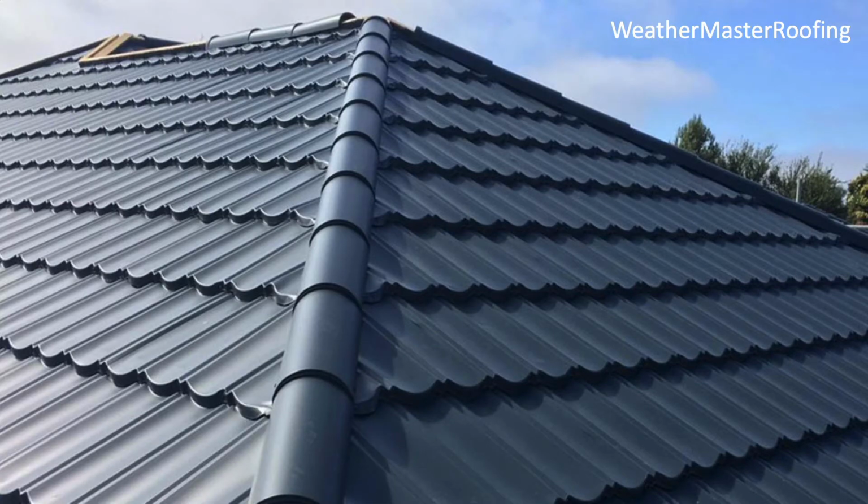So roofs do it tough. They get really, really hot. They're facing that full brunt of the solar radiation, and we know of incidences from around the world where it's been documented that the roof surfaces can reach 90 degrees Celsius, and we're getting those sorts of findings in Australia as well with some of the research that we've done. In fact, some of our monitoring equipment goes up to 85 degrees Celsius, and that's pretty much the limit of some of the sensors that we've got. So there's a good chance that our roofs are experiencing temperatures in excess of 85 degrees Celsius.